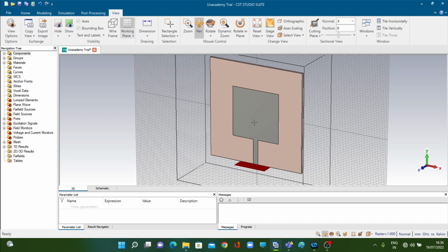Now, we will begin this structural modification by cutting slots. Or how can we actually cut slots? We can etch out. Etching means removing portion. We can etch out portions of this metallic patch and modify the structure entirely. Let's see. For this demonstration, I will only concentrate upon the patch, not the ground plane. So we need not be bothered about the back side of the substrate. So a front view of this entire structure is sufficient for us.